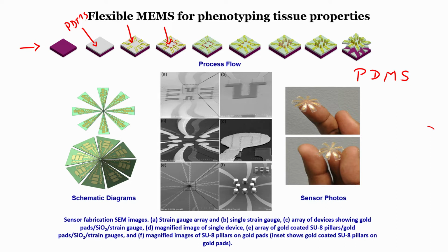Piezoresistor is made out of a material called PEDOT:PSS. PEDOT:PSS is a polymer, not a semiconductor material, which is a piezoresistive polymer. So, this is a conducting polymer, that is why I was confused with semiconductor. So, PEDOT:PSS is a conductive polymer, and it has a piezoresistive property.